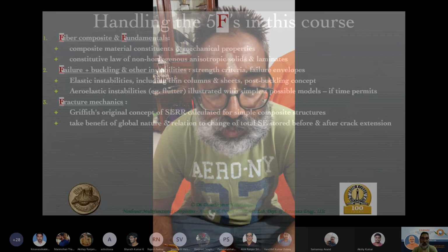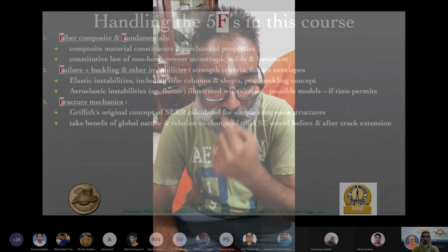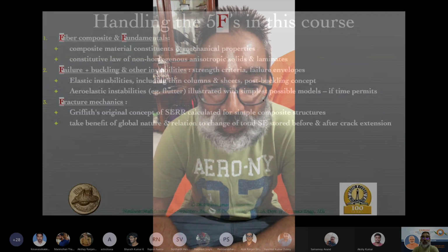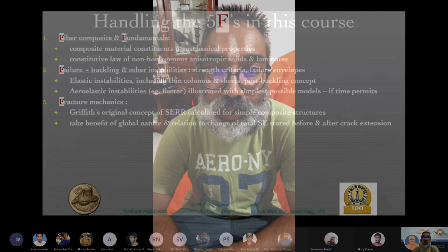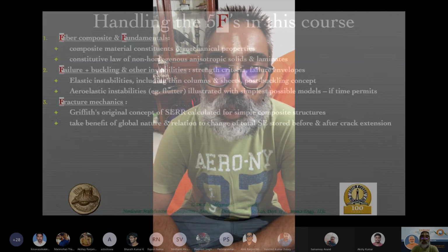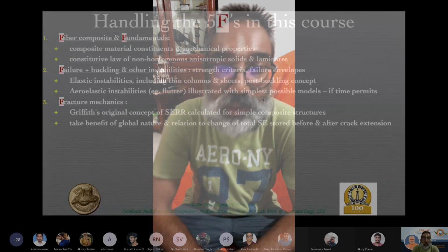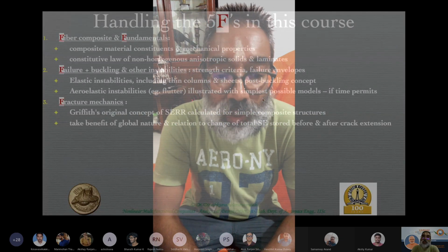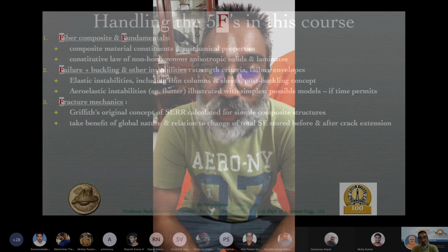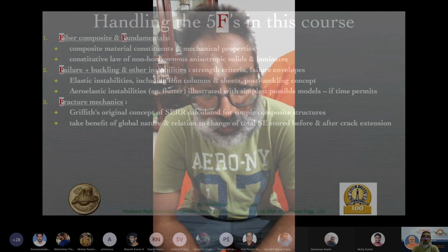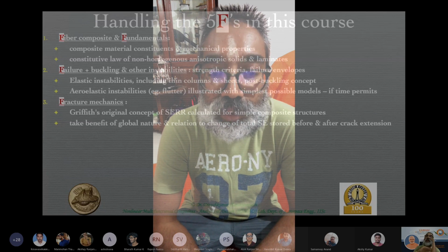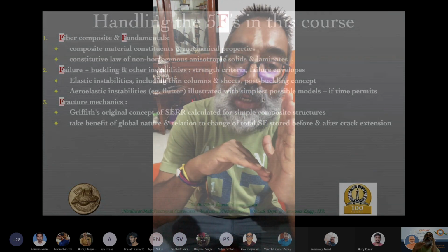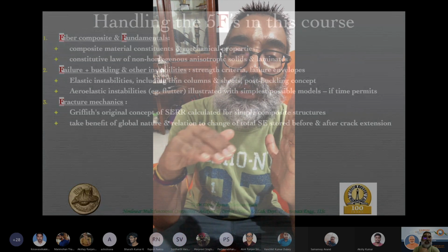See, these are two different things. Homogeneous basically means it's a point property. Anisotropy is also something related to a point in different directions. But Young's modulus basically is a material property, as you said rightly. For small strains, it is constant for most materials. But as you increase the strain, if you plot the stress versus strain, the slope of the curve can change.